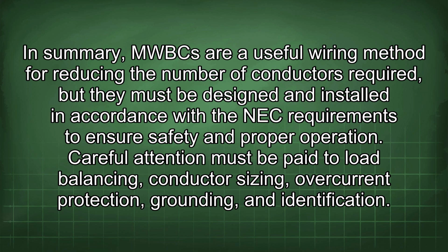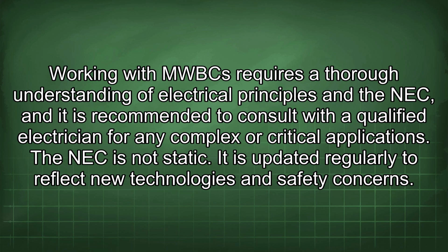In summary, MWBCs are a useful wiring method for reducing the number of conductors required, but they must be designed and installed in accordance with the NEC requirements to ensure safety and proper operation. Careful attention must be paid to load balancing, conductor sizing, overcurrent protection, grounding, and identification. Working with MWBCs requires a thorough understanding of electrical principles and the NEC, and it is recommended to consult with a qualified electrician for any complex or critical applications.